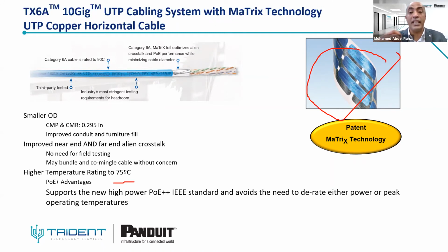The Varimatrix HD cable and Varimatrix cable have almost the same diameter as the Cat6 cable. So you don't have any concern when you're upgrading from Cat6 to Cat6A. I'm talking regarding the conduits and busways. So you have the same sizes for the cable.